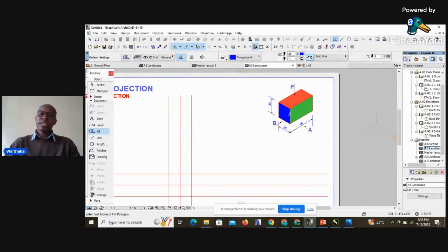The end view that is to the left, as you observe the block, whatever you are projecting, if the end view that you are required to project is towards your left hand side, then when you are projecting it, we project it to the right hand side of the front view.